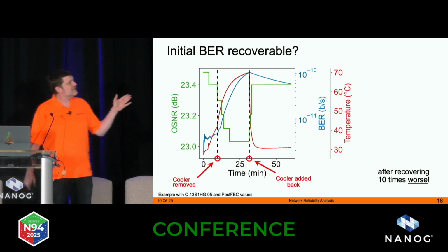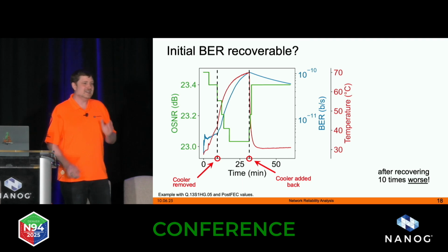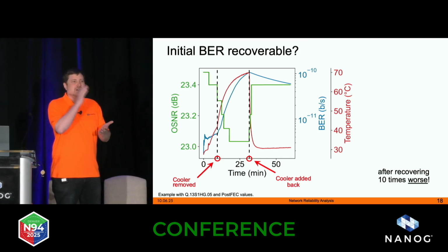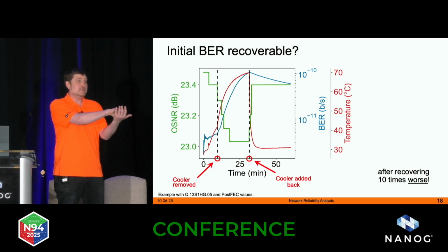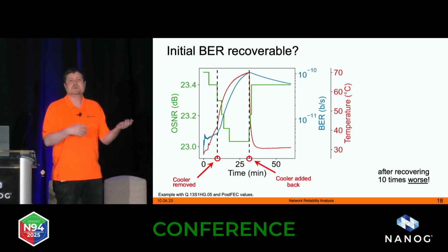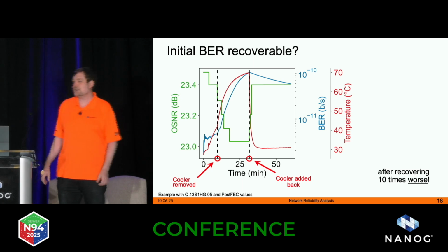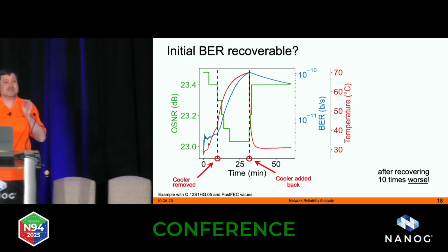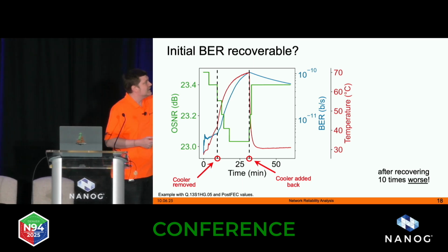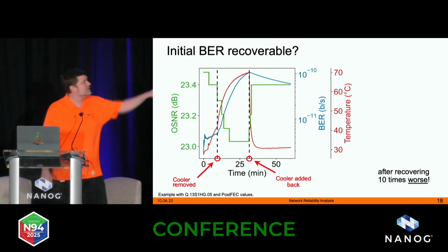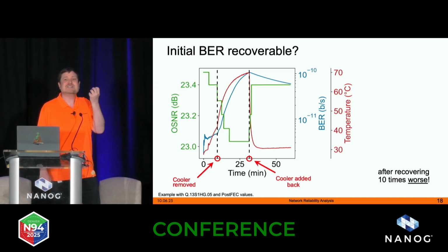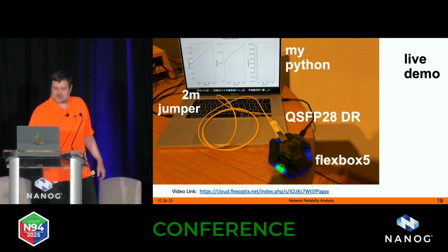And the reason for that is when you usually read it out of the register, it is a rolling average. The firmware checks the bit error rate, writes it into the register, and takes the old value, the current value, adds the new one, divides by 2, whatever the rolling average does. And you have to keep this in mind. You can reset the transceiver, plug it out, plug it back in, and you get the original values. But if you don't do that, you are dragging history with you. So just keep this in mind.